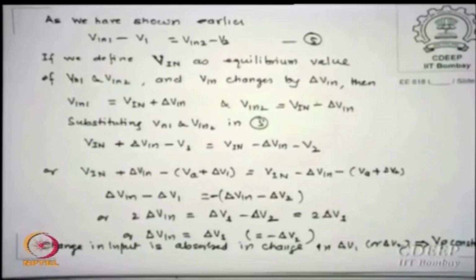So Vp still remains constant. Any change is taken care of in the Vgs value and not in the Vp value. Is that correct? Delta V1 absorbs the change in Vin. Okay. See, the average value of Vin1 is, let us say, something. So if Vin increases beyond this or goes below that, from some value I am assuming, like a DC level plus AC kind of thing, we say any change in Vin from a given value always gets absorbed in those V1, V2 values, delta V1, delta V2, and does not affect Vp at any time. Is that correct?